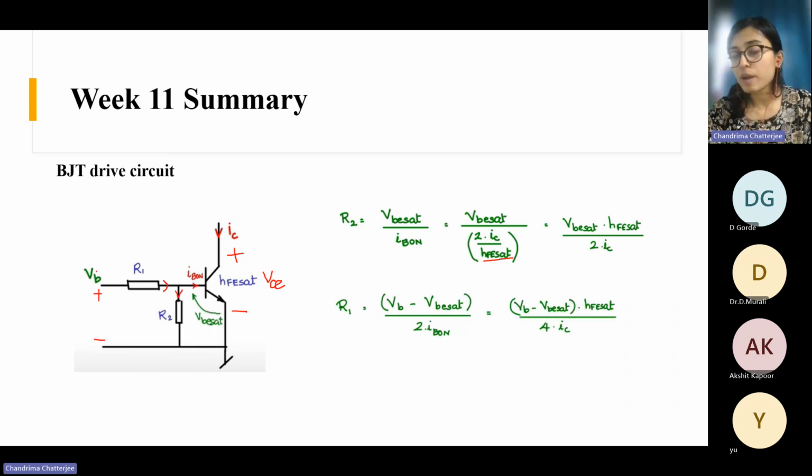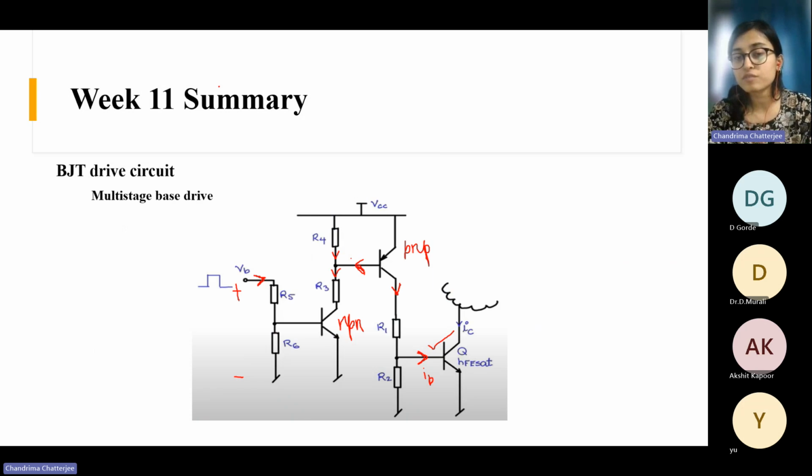Current rating, then its power rating should also be high. If I assume the voltage is fixed, then for a higher current rating, its power rating will be high and then it will be very expensive, right? Compared to this power source, the cost of these extra BJTs will be nothing, just this BJT and resistor.